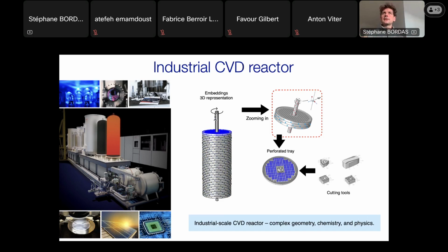If you remember, when we tried to non-dimensionalize everything, if you use that, you see that the flow is going to be laminar because the distances between things, so the length scale, is quite small, and that is going to lead the Reynolds number to stay relatively contained. So we're not blowing things at 200 kilometers per hour at huge concentrations over very large distances. We have a very small distance between these different inserts, and this is the way it looks.